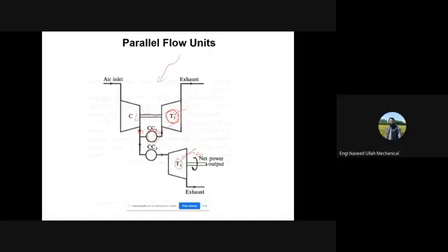And then after that, the same bleed is given to combustion chamber 2, and you can add heat and you can have the combustion over here, fuel, spray fuel over here according to the requirement of this turbine 2, right? So they are independent of each other. Let's say, for example, the requirement of this turbine T1 is to produce X amount of work. Okay, so you can use a proper combustion over here, and you can use this much heat addition.